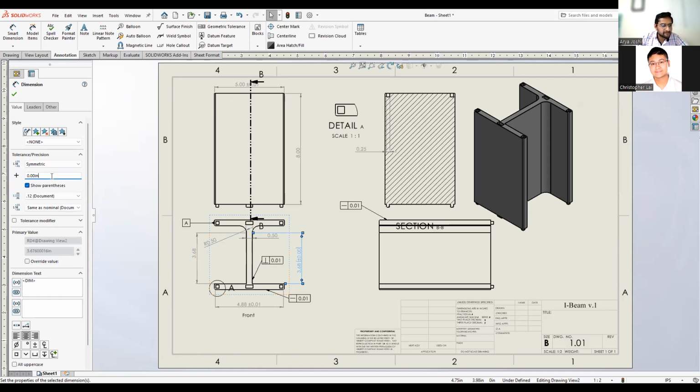And also, I forgot to mention this when I was doing tolerance for the first time, but when you go here, you can choose the digits you want. So if you want more precision, then maybe you can choose up to the thousandths or 10,000ths. But in this case, the hundredths is pretty okay for us, but those are the options there.